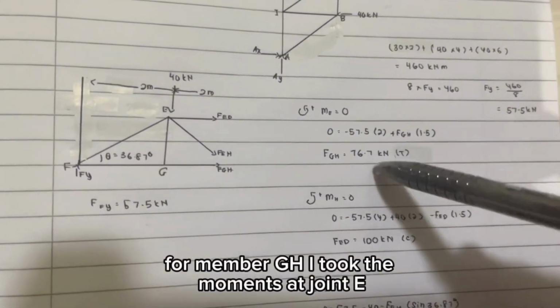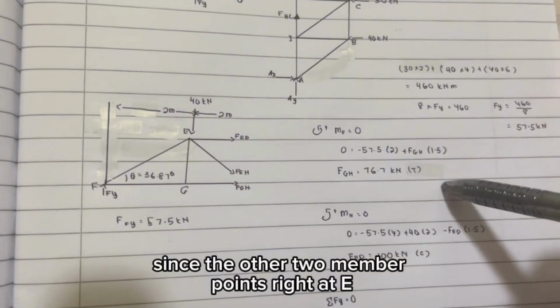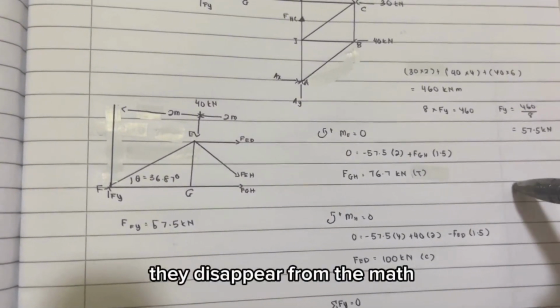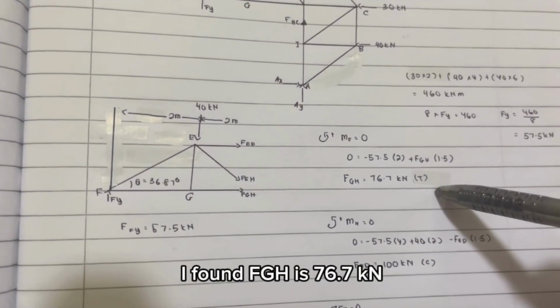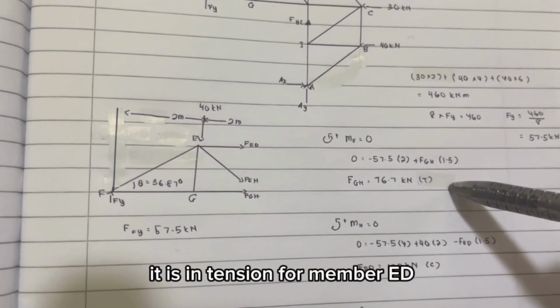For member GH, I took the moments at joint E since the other 2 members point right at E. They disappear from the equation. I found FGH is 76.7 kilonewton. Because it's pulling away from the joint, it is in tension.